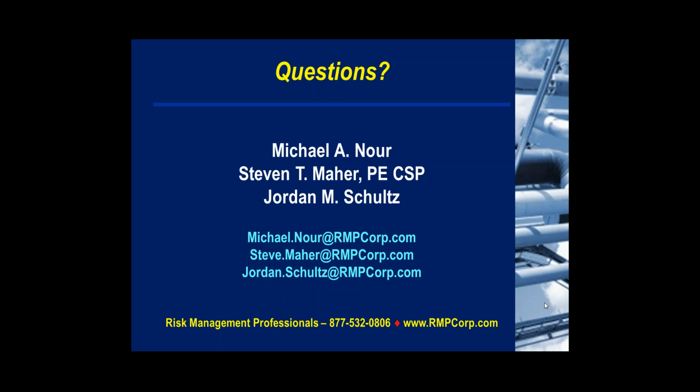I'll build on that a little bit too. A lot of you have to deal with layer of protection analysis and also defining SIL levels for your safety instrumented systems. By doing an IPHA approach, it basically puts everything together, so the team has some consistency in how they address consequences. They can put in various factors to address likelihood of mechanical failures, and if you have other active safeguards that are safety instrumented systems coming into play, you've got a uniform approach for that, so you're not missing something radical or overrating your SIS.